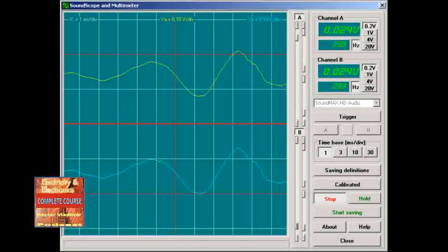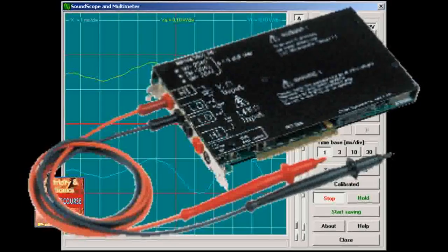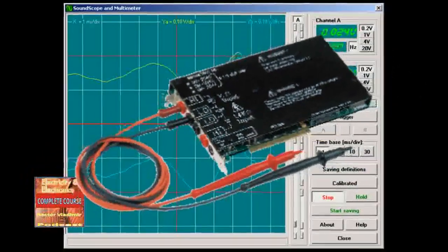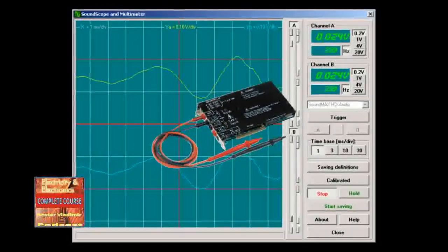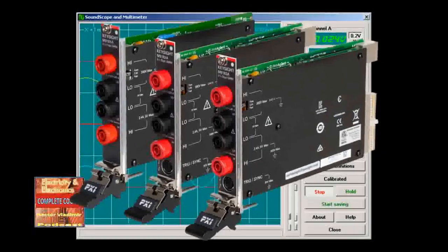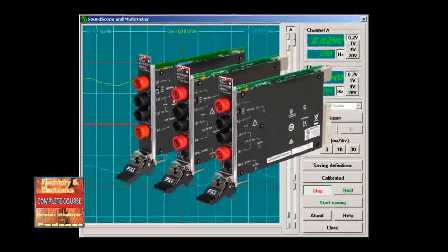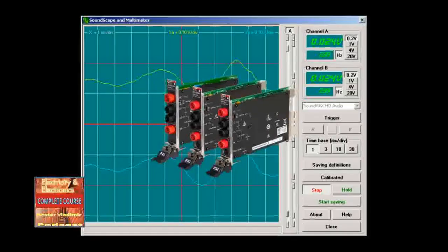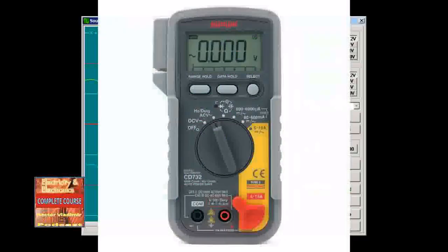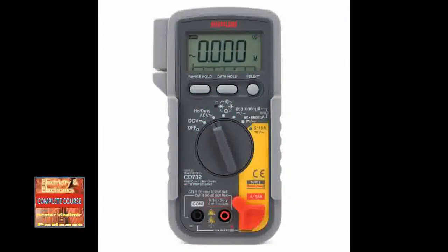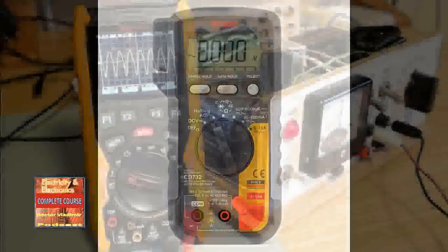Some manufacturers offer interface cards that can be installed on a personal computer and have test leads similar to meter leads. After the interface board is installed in an expansion slot in the computer, software is loaded. Now the computer will display a simulated meter on the monitor. The computer can then be used to take voltage, current, and resistance readings. Using the computer is very similar to using a digital meter, but with the computer you can use the memory and hard drive system to store measurements and retrieve them later. This type of metering equipment is commonly installed in new industry applications to monitor high-speed assembly equipment or to test electrical parts.